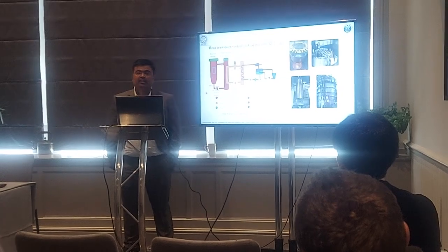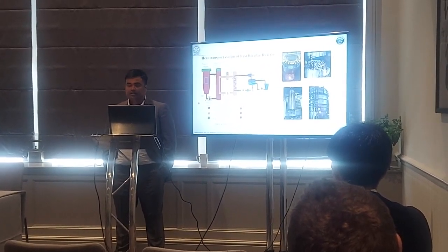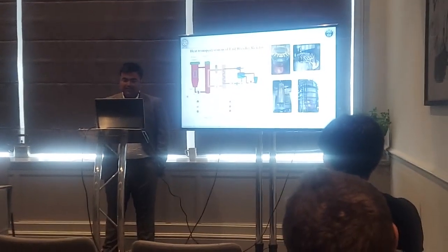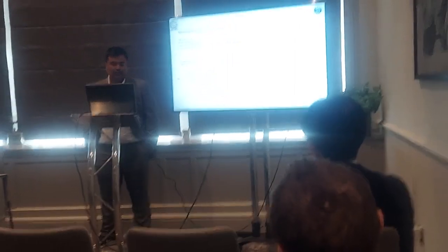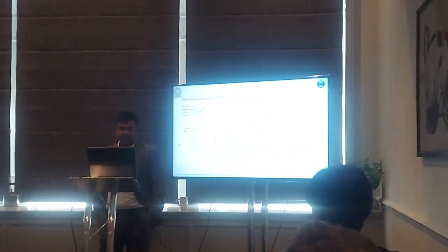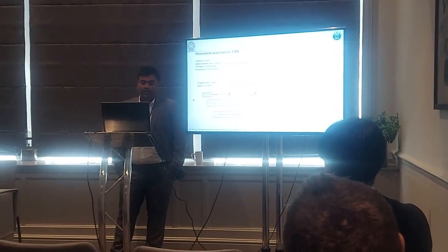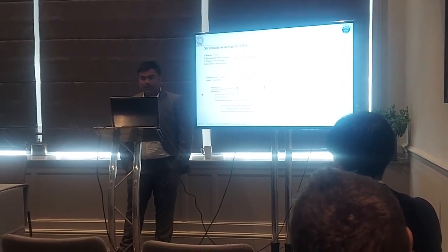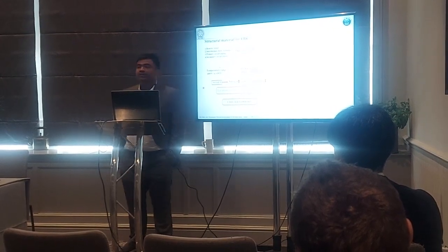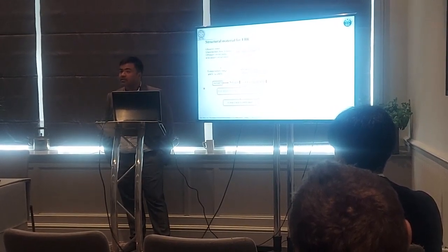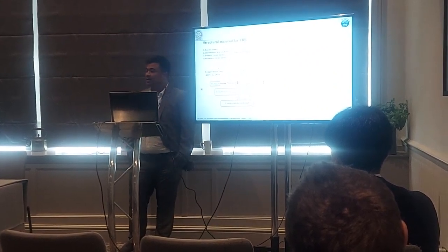For all these considerations, India is using, for the reactor vessel, intermediate heat exchanger, primary sodium circuit pipe and secondary sodium circuit pipe, where the working condition is 400 to 650 degrees Celsius and very low pressure, the SS316 LN. In a previous talk, we heard about SS316 LN.